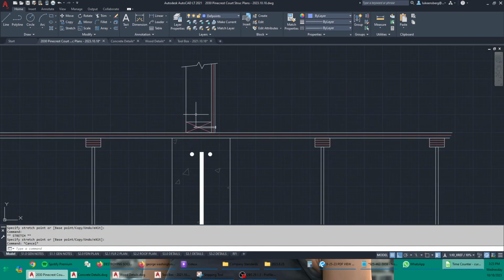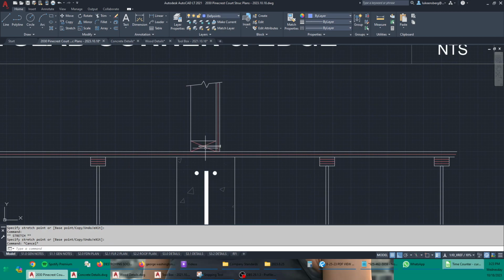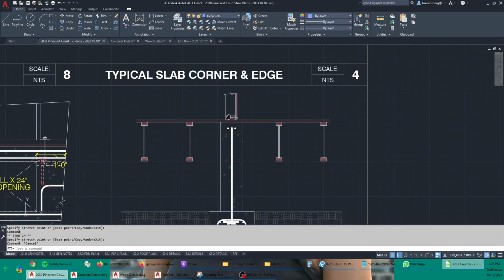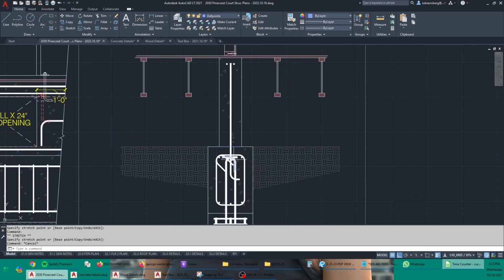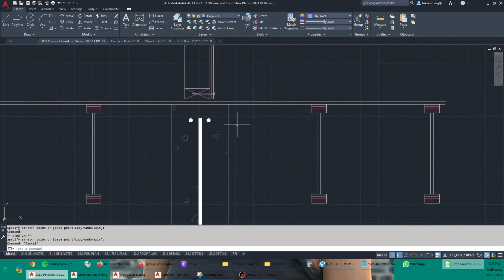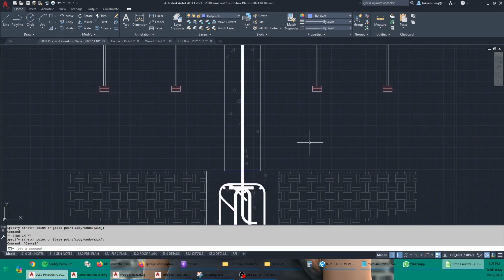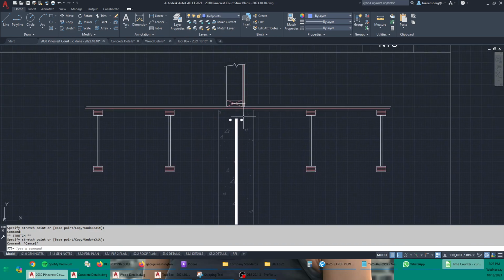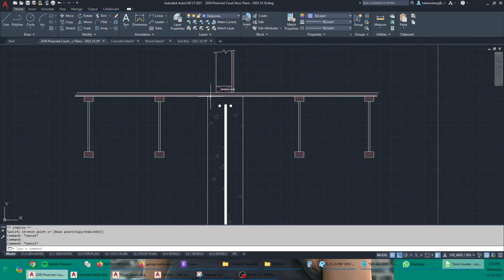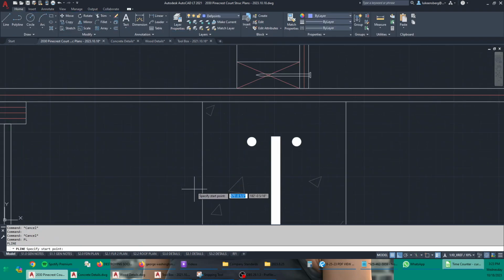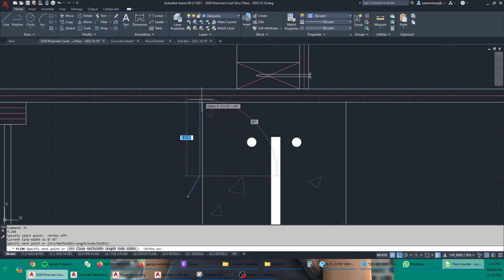All right, so we've got here our wood wall sitting on top of the sheathing. One problem with this is that this is going to wick moisture up. This concrete stem wall will wick moisture up from the soil into the plywood, and the plywood then can mold and rot. So what I'm going to do is draw something called flashing here, like this.